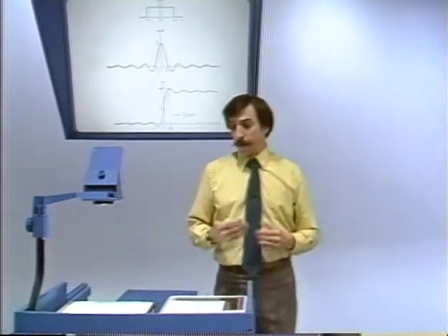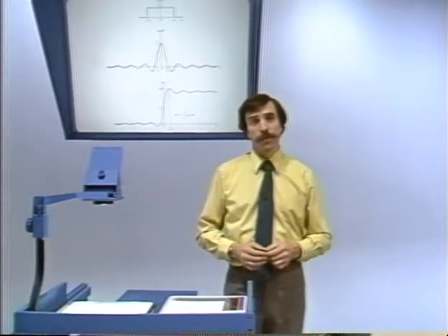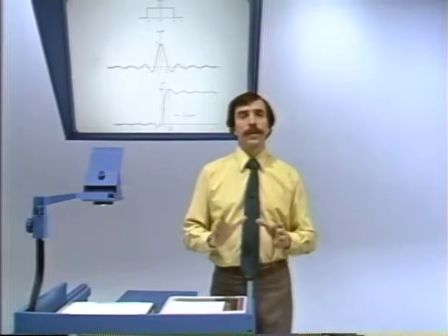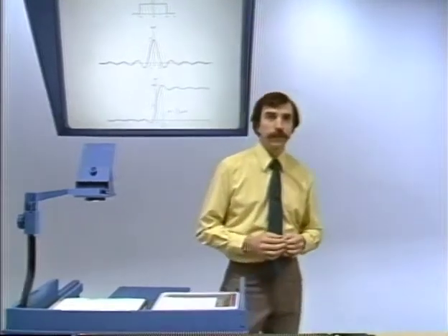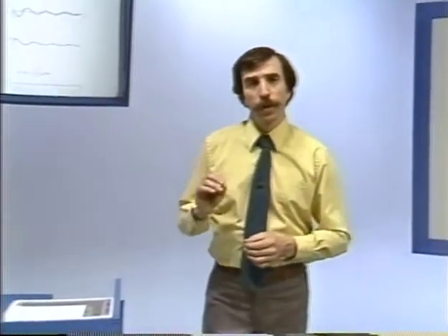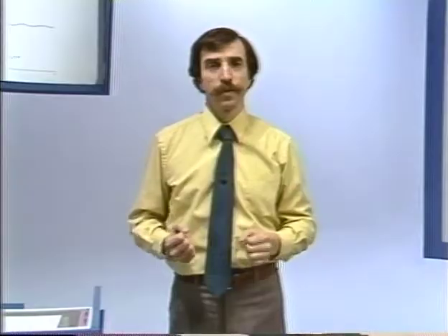Now, there's another very important point, which again we can see either in continuous time or discrete time, which is that even if we wanted to have an ideal filter, the ideal filter has another problem if we want to attempt to implement it in real time. What's the problem? The problem is that since the impulse response is even and in fact has tails that go off to plus and minus infinity, it's non-causal.